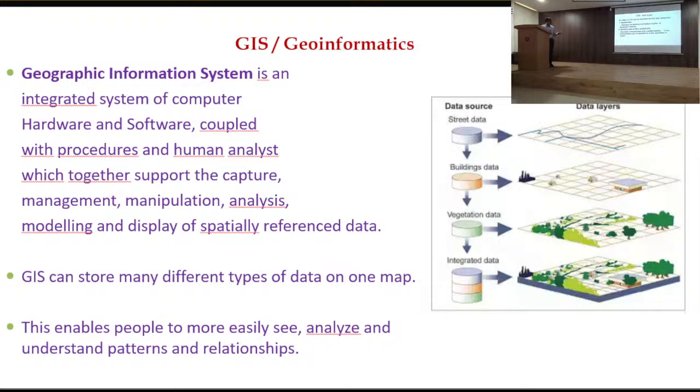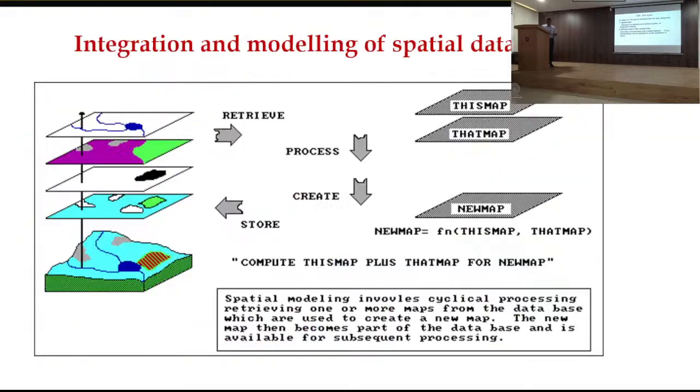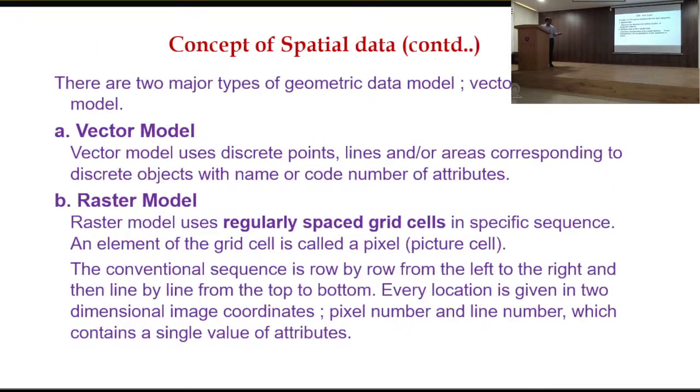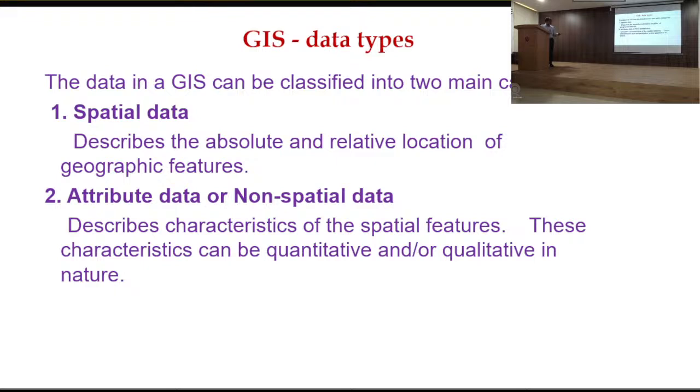Now as I told you in the beginning of the lecture, GIS deals with spatial data. To make spatial data, we need the location details, whether it is XY, XYZ or XYZT. Whatever the fashion, the minimum is XY, which means latitude and longitude. Then there is the attribute data, the non-spatial data, which is secondary data or additional details of the spatial data, explicitly tagged with the spatial data to qualify the attributes.